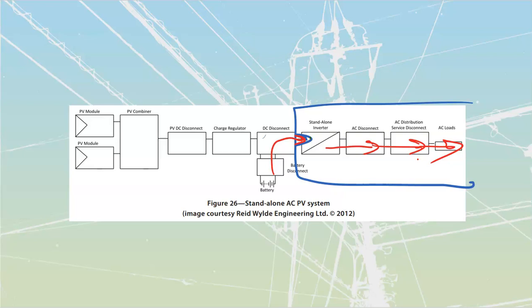By the way, for first responders, they do have blankets that are fairly thin, but they're going to be completely opaque, and they'll put them over top of photovoltaics. If they don't know what's going on, the guaranteed way to shut off the PVs is to stick a blanket over top of it. If you ever work in photovoltaics, buy yourself some good tarps so that you're able to cover over stuff. A tarp and a bit of duct tape, and you can make sure that a system is going to be shut off while you are working on it. Don't get a see-through tarp, don't get one of those light blue ones that the light passes through. You want to get one of those heavy black tarps or the silvered ones.